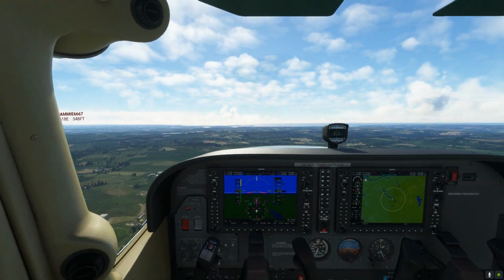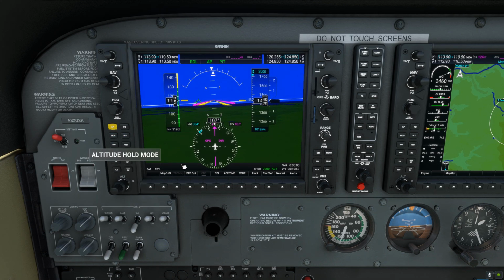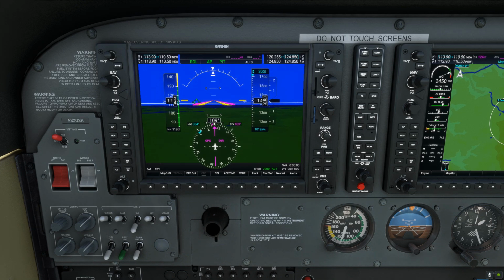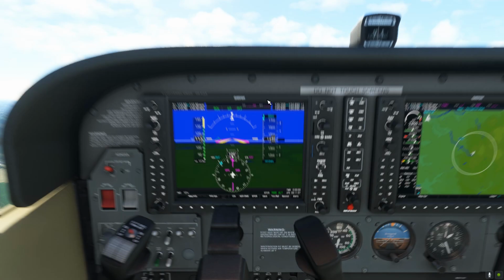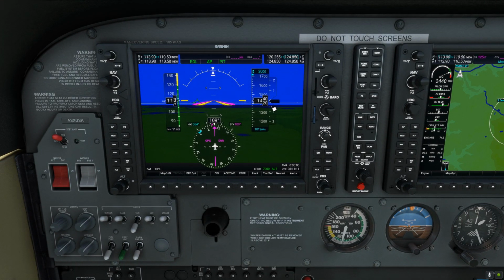That'll do. So if you set an autopilot altitude, let's say 3,000 feet, and press your autopilot button, it doesn't always climb. Look, I press autopilot, it's in autopilot control, I've set my altitude, but nothing's happening. Because if you're leveled out, or near leveled out in flight, whenever you press that autopilot button, the state of your aircraft, so if I was banking left or right, or I'm in level flight like this, it will keep that state.